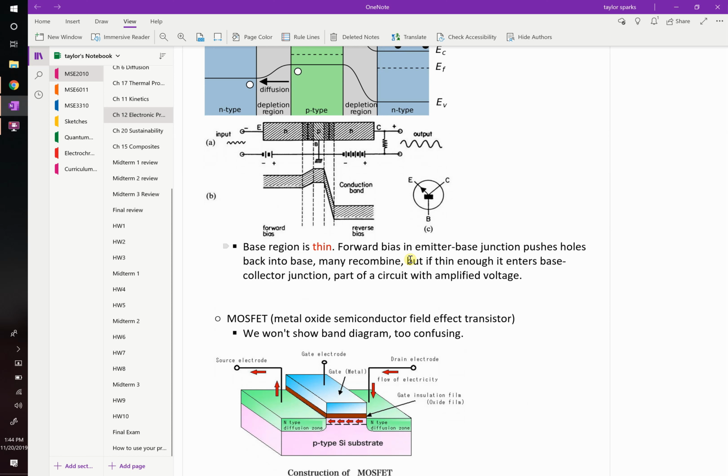How does it work? You start out with a P-type substrate, so it's all filled with holes. Then you implant a region, and you're going to do this on the homework that I've assigned, where now you have an N-type region by implanting it or diffusing in extra electrons. So you've got holes, electrons, electrons. If you put a voltage across these two things, you'd like to make your electrons transit from here to there. And in doing so, you can store memory, right? Flash memory works like this. You can either store information as traveling between these or not.